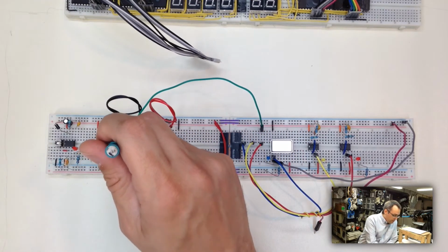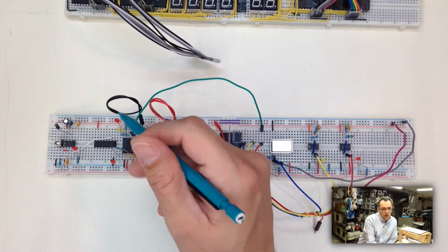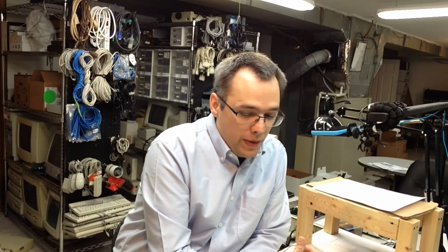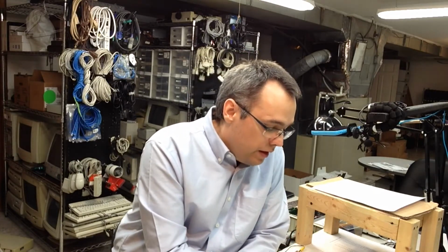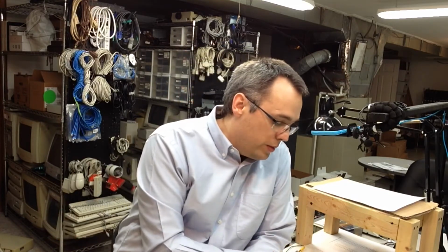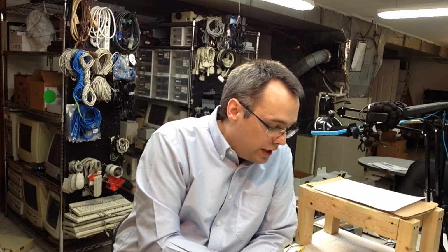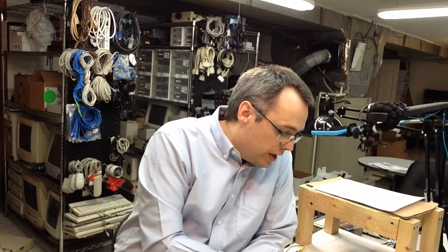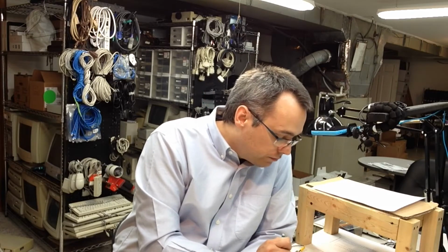Quick reason why the 6502 needs that. When the 6502 powers on for the first time, and many of its support chips as well, they will all power up in a quasi-unknown state. Basically, it's just a monolithic slab of void when you turn it on, and it doesn't get set to anything when it's powered on. But when you pull the reset pin low, it basically yanks all the circuitry back to where it needs to be internally and puts it into a known state. So that's why you have to do the reset on that.